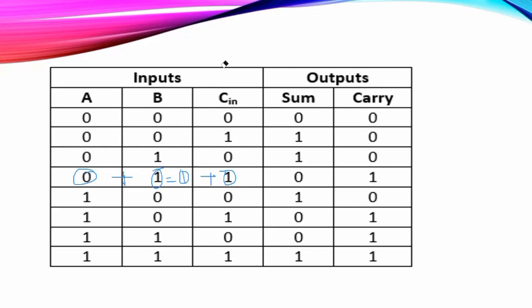So when these both the inputs are added together, A and B, when they are added, 1 plus 1. So I told you 1 plus 1 is nothing but 1, 0, which is 2. So this is carry and this is sum. So to the sum bit, we will be adding 1 to it.